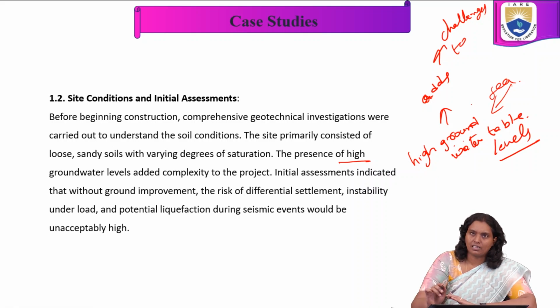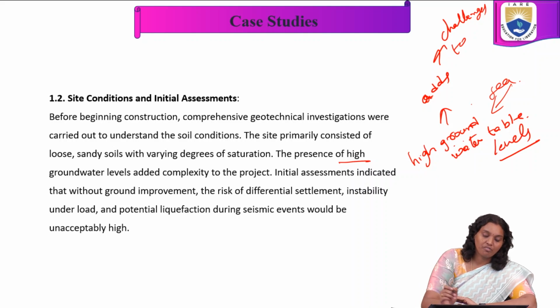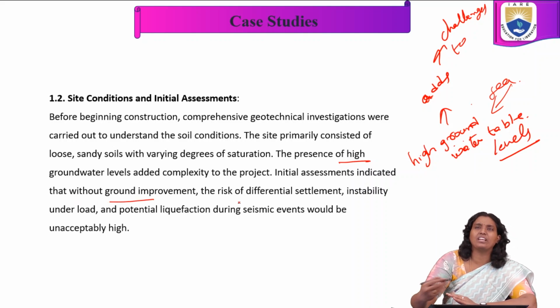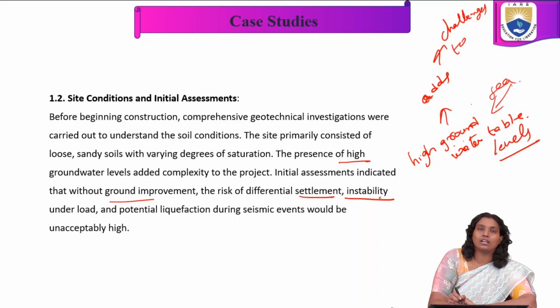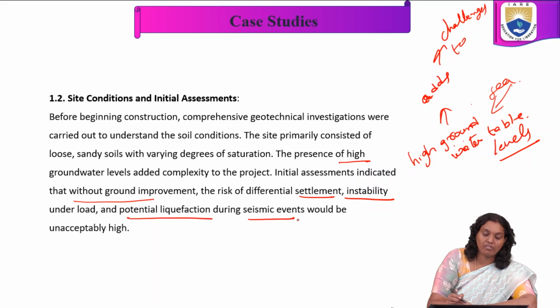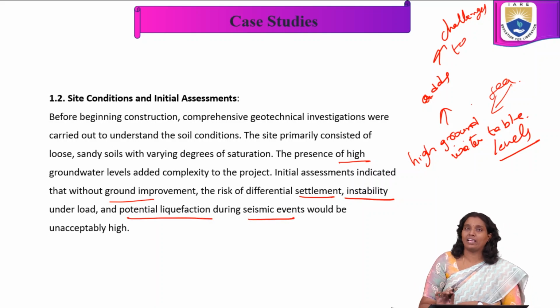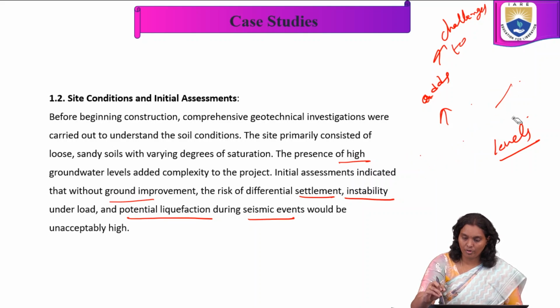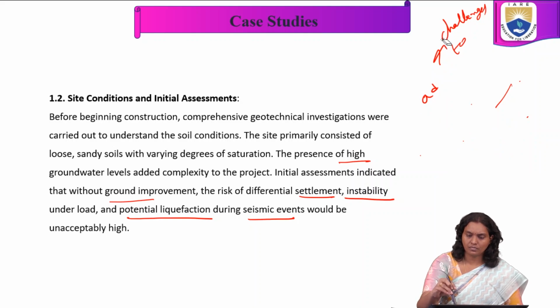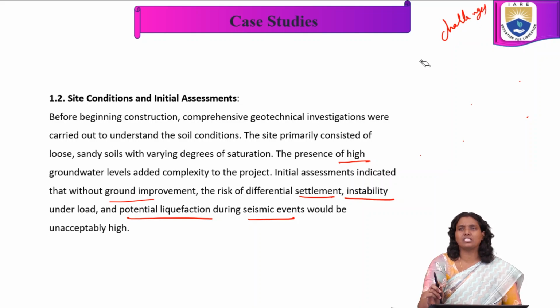So because of these complexities, initial assessments indicate that without ground improvement, the risk of differential settlements, instability under load, and potential liquefaction during the seismic wave would be unexpectedly high. But it is important to the country's economic growth, and it is the major port and also a prestigious project, where international trading is happening. So these are all the parameters we have to understand in this site condition.